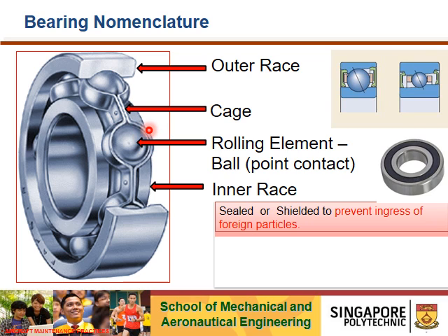All right. So yeah, and not all bearings come with a cage. In this case, this setup with a cage is a fixed point ball bearing. That means this ball bearing will actually rotate on the spot and prevent axial movement. If there's no cage, then the ball rolling element itself is actually floating and able to move around and rotating. Okay, so that's just a design.